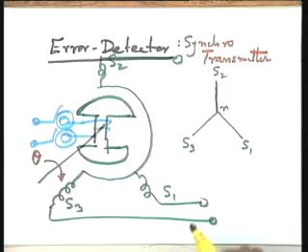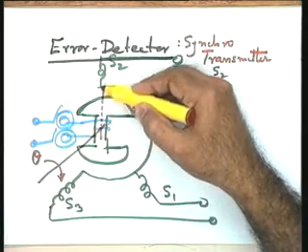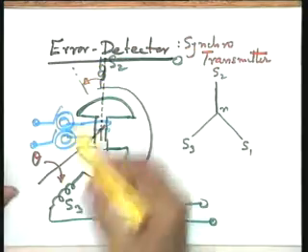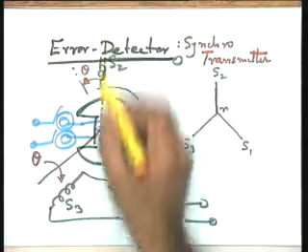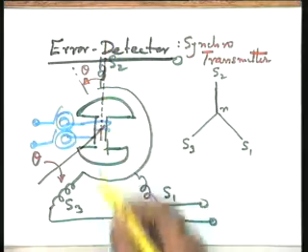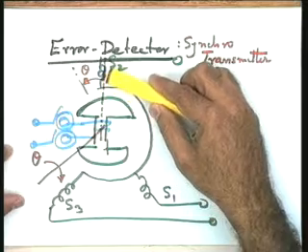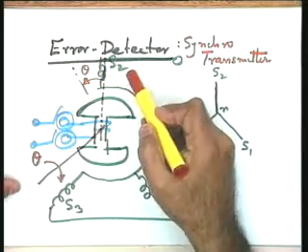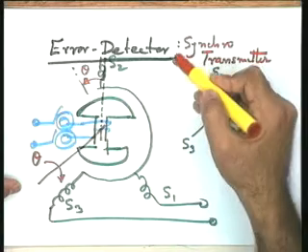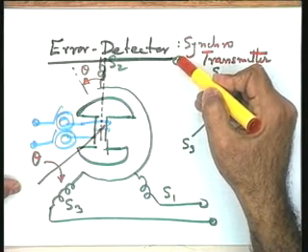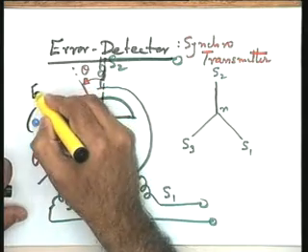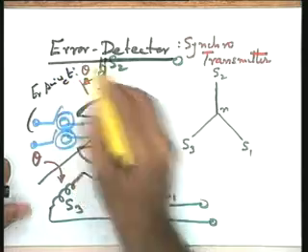In this particular case you will find that the rotor angle over here, theta, let me take, taking this S2 axis as the reference, and with respect to this reference I take theta. If theta is equal to 0, the maximum flux is linked with S2, and therefore maximum voltage will appear over here. If I take this voltage to be ER sin omega_c t, what is the voltage across S2 please?